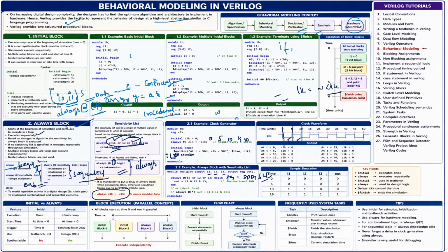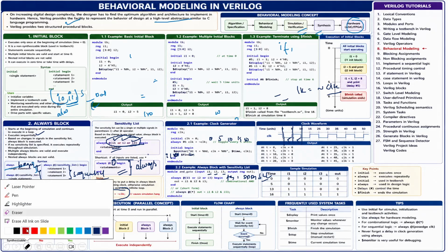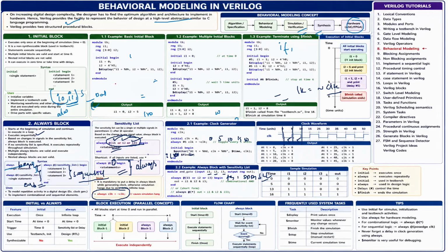And this is the basic example for the initial begin block and then the always block, whatever blocks we are using. See, initial begin is utilized on the testbench side. See, module TB. I am declaring the register inputs, input 1 and input 2. Input 1 is a single bit and input 2 is 4 bits. I am assigning some values here and displaying that. Just an example for initial begin.